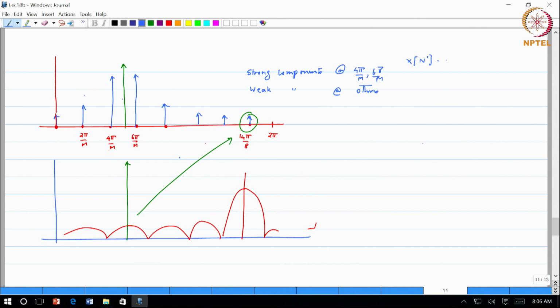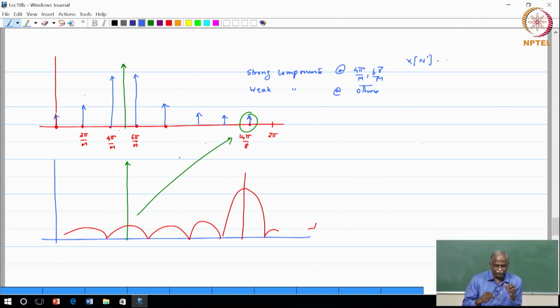If my input signal has a single tone which lies in between two DFT frequencies, you will find that all of them have non-zero values. What is puzzling is why a frequency component which is far away from my tone would still show something non-zero. The reason is that it is not a delta function, it is actually a filter that is looking at the input spectrum. So some component comes out of it, and that is what shows up as the DFT coefficient.